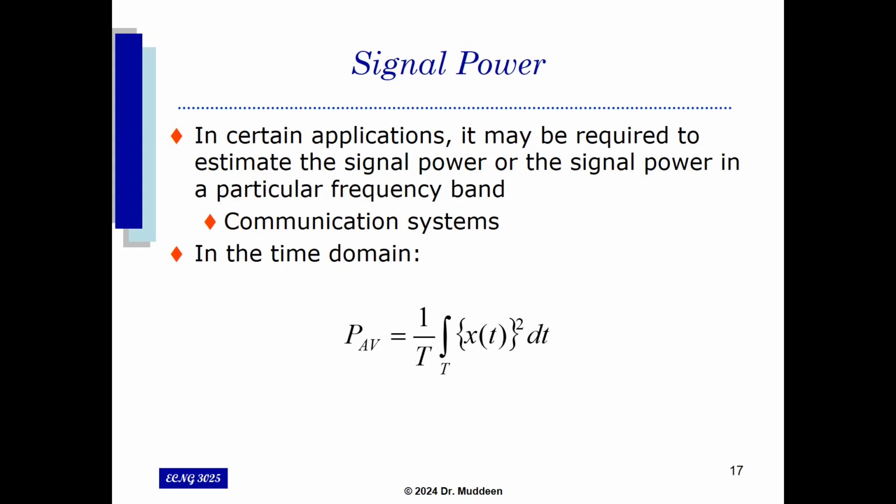For instance, in Trinidad, if you were to buy a set of two-way radios, walkie-talkies, from the mall, by one of those electronic places, or Courts or PriceMart, those, in order to operate in the frequency band that they operate, which might be in the high VHF or low UHF band, you are restricted in how much power you have. I think it is 2 watts. So you can't broadcast with more power than 2 watts in that particular band.